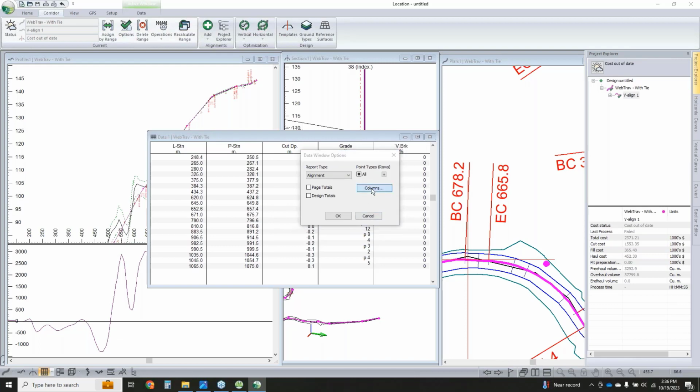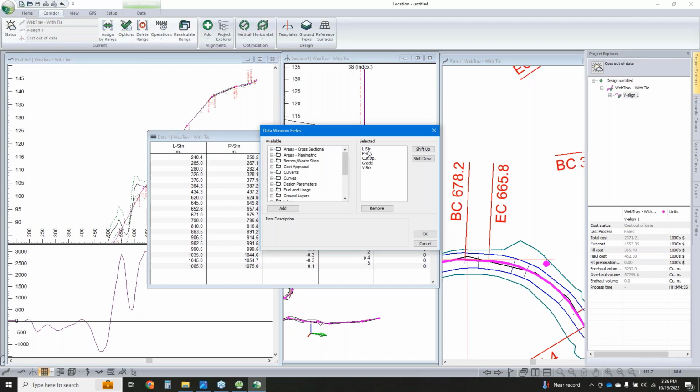We're going to choose the information we'd like to report here. We want to see it all relative to our index number. I'll leave these just to note the difference in length. But let's go in here and we'll go horizontal offset, and then down to our slope stakes, and we've got our P stake left and P stake right.